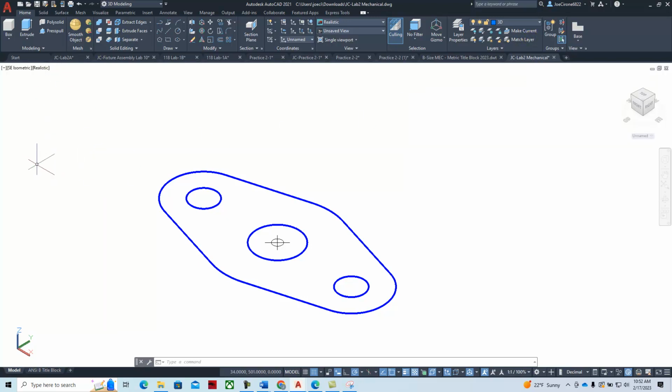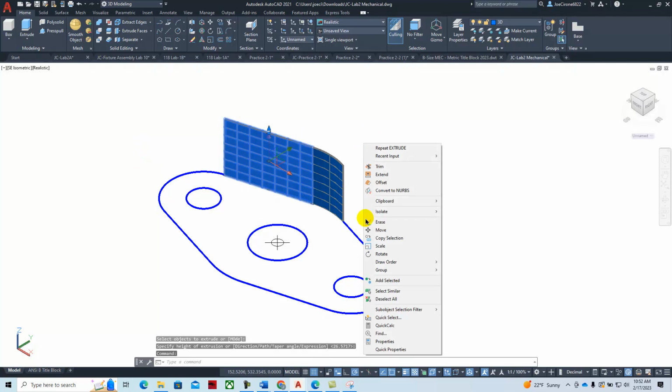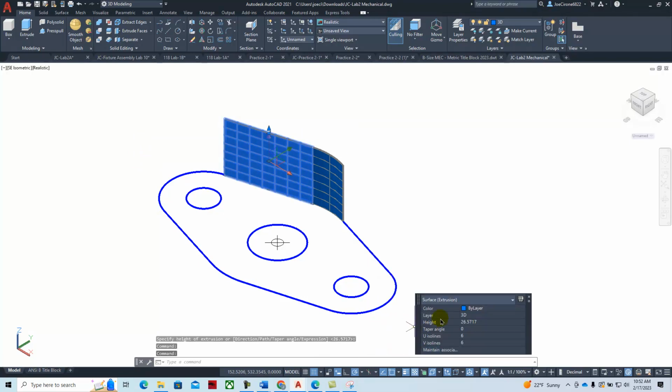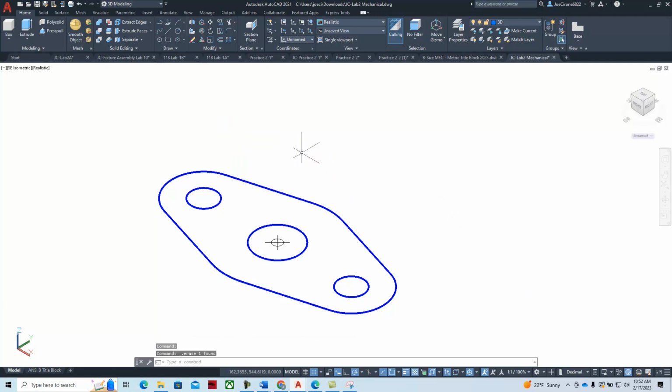So as I go through, if I were to extrude this, what happens is I get something like this. And these are valid shapes for surfaces. And surface modeling isn't going to allow us to do 3D printing. It's good for CAD CAM, but we want to use solids. And so that's the difference between the press pull command and just the straight up extrude command.